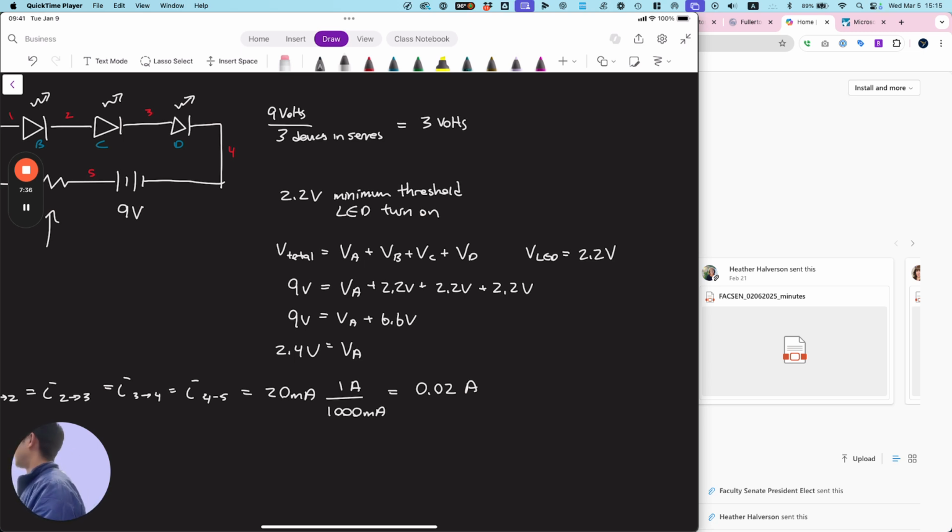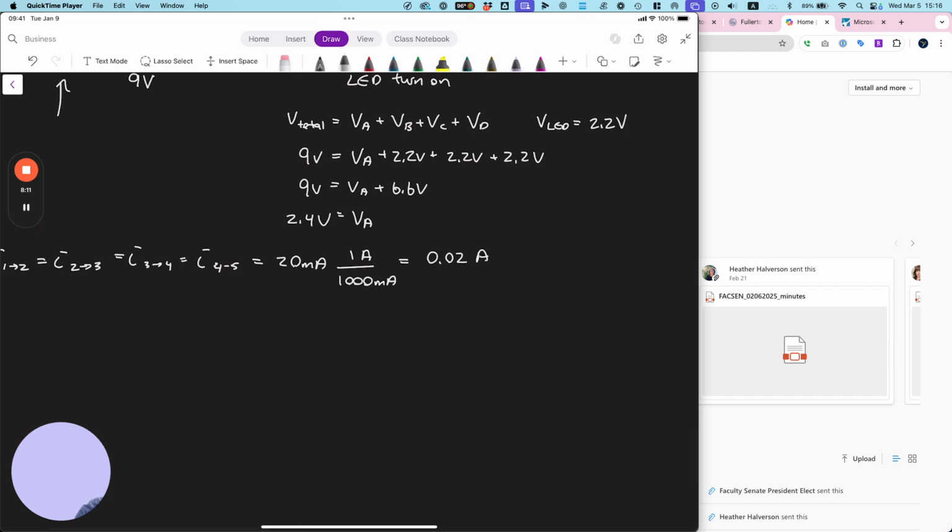Okay, so I'm converting it to amps because when we do something like, remember that law? I don't want to say it because I want you to figure it out. Ohm's law, yeah. V equals IR. You can do things with different scales of units, but then you have to keep track of that. Versus if you keep everything at the baseline, like times 1, voltage, not millivolts, not kilovolts or anything like that, then you can just keep using the same non-scaled version. Okay, so we have V equals IR, Ohm's law.